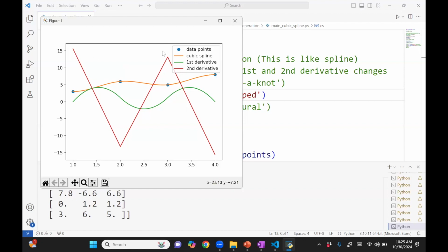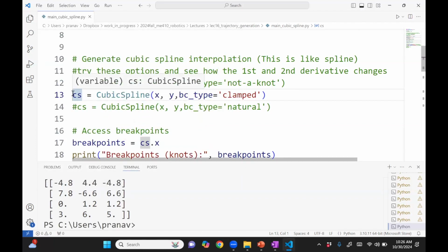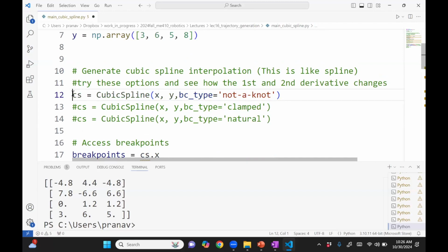Okay, so it achieves the same objective of taking the points through the orange, but then it has a very different acceleration. It just means different things for a motor. Also, the energy usage will be different if you have different profiles. One of them might be more efficient than the other one. That's something you need to check based on your power dissipation in the specific motor. You might have a hydraulic system in which the power consumption will be different from an electric motor.